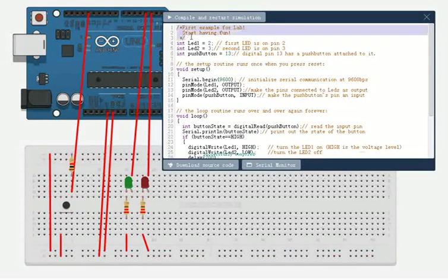Here the first thing: it's a very good idea to start by commenting your code. In Arduino, you just use // for single line comments or /* for multi-line comments. We call this first example Lab1 and start having fun. At the beginning of the code, we have this line to say int LED1 equals 2. So this creates a constant called LED1 that contains the value 2.